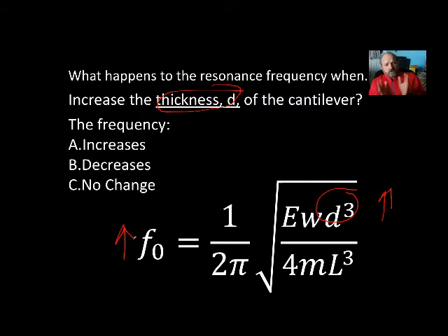Okay, and that's what you should always do with these simple equations, is just look at what happens. If I change this, what do I expect? If I change that, what do I expect? And get a feel for what you would expect to happen. And then that way, when you do your experiment, or you're utilizing a cantilever sensor for something, or designing a cantilever to be part of a system, or if your system has a cantilever in it, you have to think about the resonant frequency and what happens if it gets longer and if it gets shorter and that sort of thing.